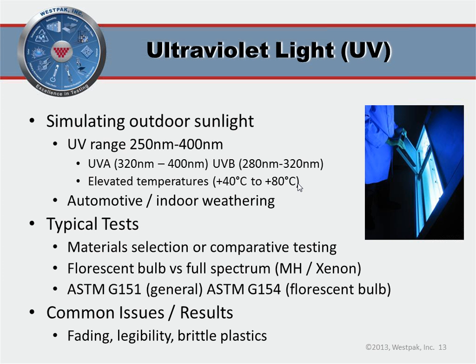Or commonly comparative testing is done. If you have different material choices or processes, test them all, see which one does the best. After testing, think about post-test mechanical testing, so things like tensile pull on plastics, or optical or other more qualitative pass-fail results. The test chambers themselves, the two common ones today are fluorescent bulb, which is what's pictured here, or